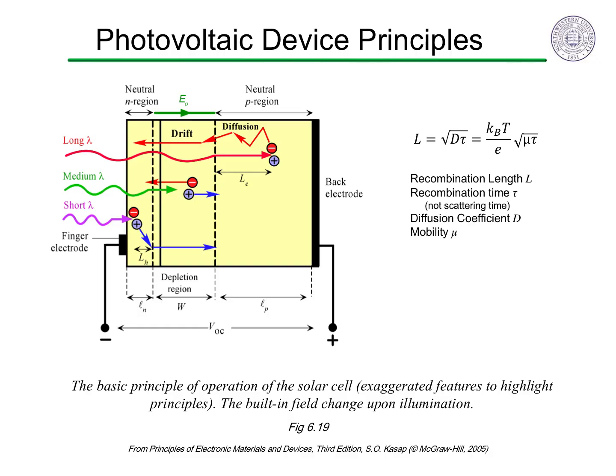Photogenerated majority carriers are repelled from the space charge region and contribute to the photovoltaic power by thermalizing in the neutral region of the electrode. Thus, it is the photogenerated minority charge carriers that are critical to engineer in a photovoltaic. The thickness of the neutral regions should be larger than the minority carrier diffusion length, or there might be significant depositing of undesirable charge at the electrode or non-radiative recombination at the surface.